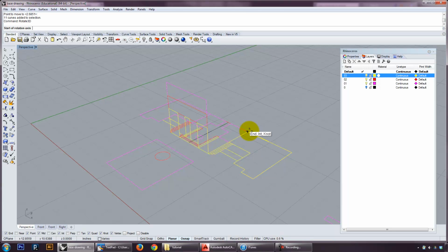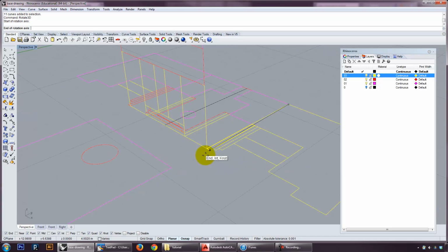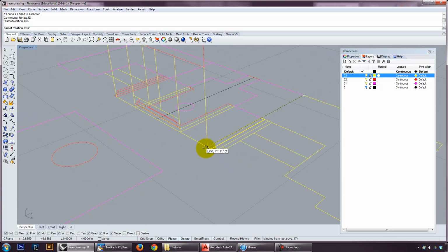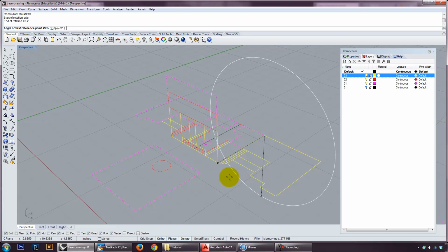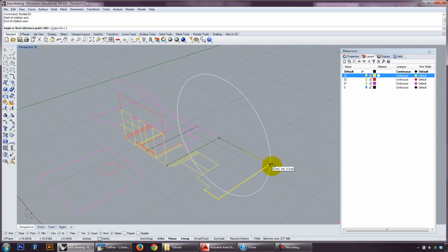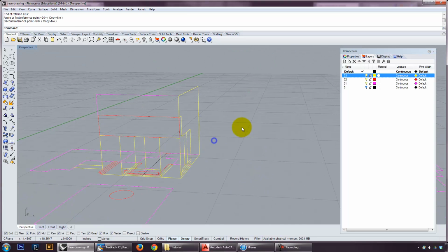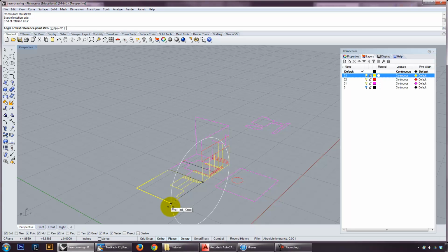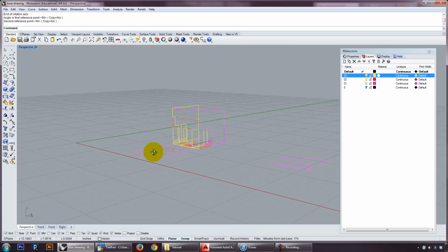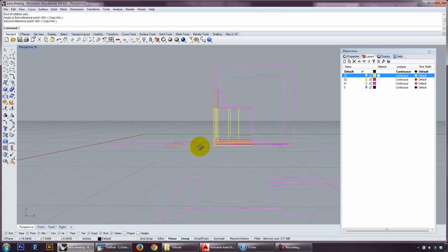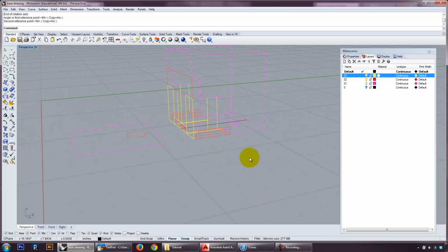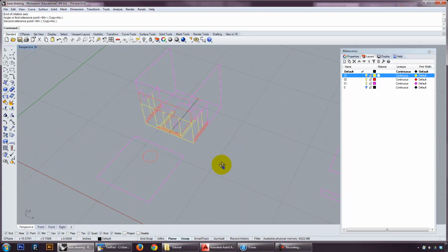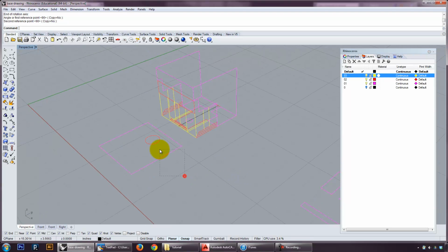So the rotation axis in this case is on this side. Be very careful to have snaps, and only the snaps you need, when you do this. You don't want to be imprecise here because it's going to cause things not to line up. Snapping here, snapping up, and then to do the same thing on this side, this angle to that angle, and you can see them starting to line up with each other. You start to see the column, starting to see this volume here.